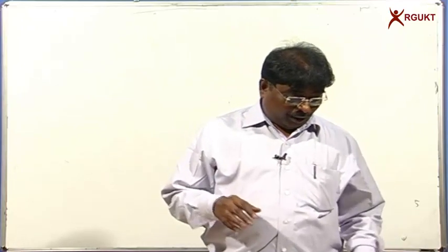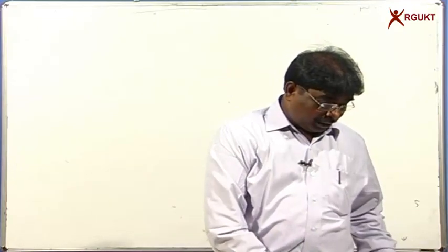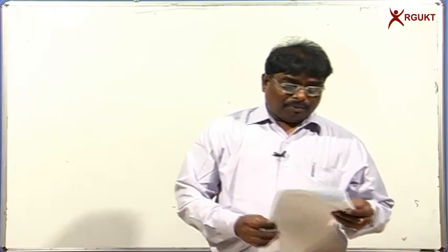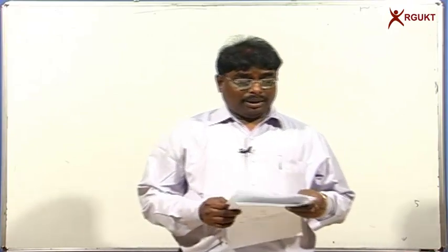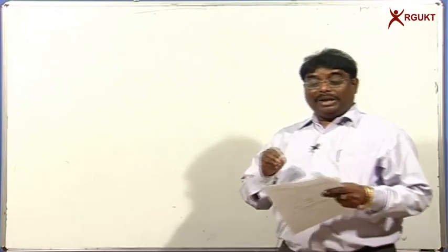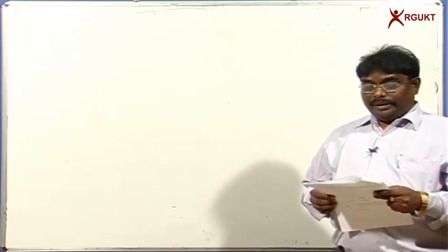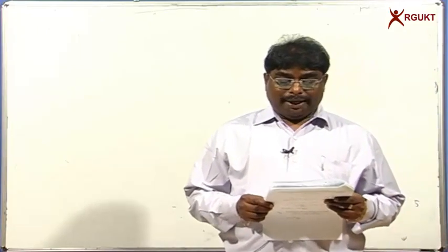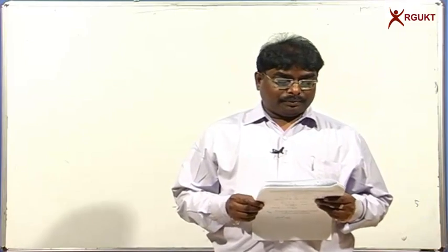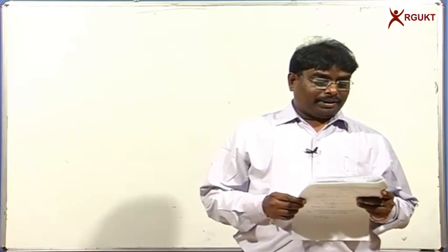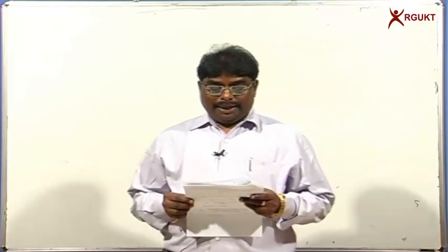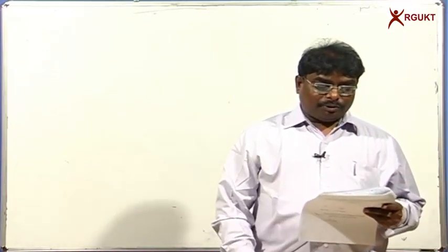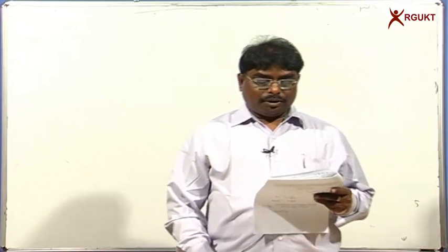And today we are going to discuss how to estimate the diffusion coefficients. One problem I will read for you. I don't want to write it here because I am leaving the material with you. Estimate the diffusivity of N-butanol vapor through air at 1 atmosphere pressure and 59 degrees centigrade. The data given: the molecular weight of N-butanol is 74, the molecular weight of air is 29.